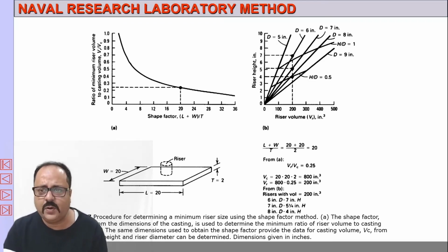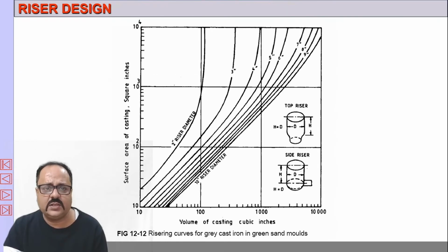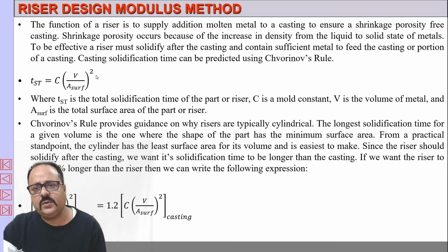But a much more popular method is the Modulus method. Now what is this Modulus method? The Modulus method is based on Chvorinov's rule of casting. Here it is the solidification time of the riser. We'll design in such a way that the solidification time of the riser is at least 20% longer than the solidification time of the casting.